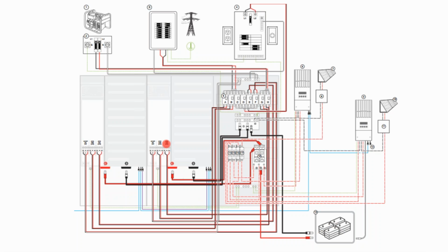So then your inverter is sized to the voltage of the battery bank as well. A lot of residential off-grid inverters are 48 volts, although the SolarEdge inverters, based on the higher voltage lithium-ion batteries, are more around a 380 volt nominal. So we're taking that battery voltage and connecting it to the AC side through our inverter. We're coming in through the DC side and going out through the AC side